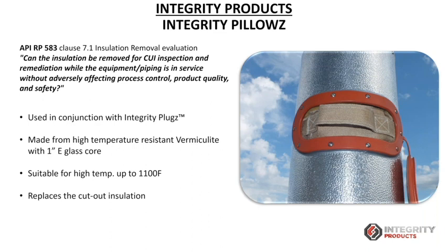Either the insulation is not restored properly, or in the worst case scenario, we can find it missing from that location. And the third is that if we are frequently replacing and putting back the insulation, doing the inspection and putting it back, it can get wet with time, and it can lose its efficiency. So definitely we need some system in place that can retain a heat barrier and the moisture barrier in that location.